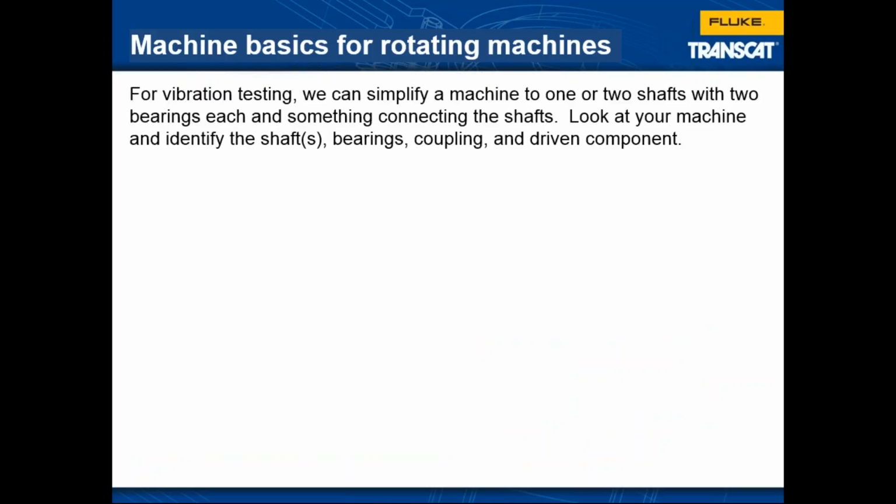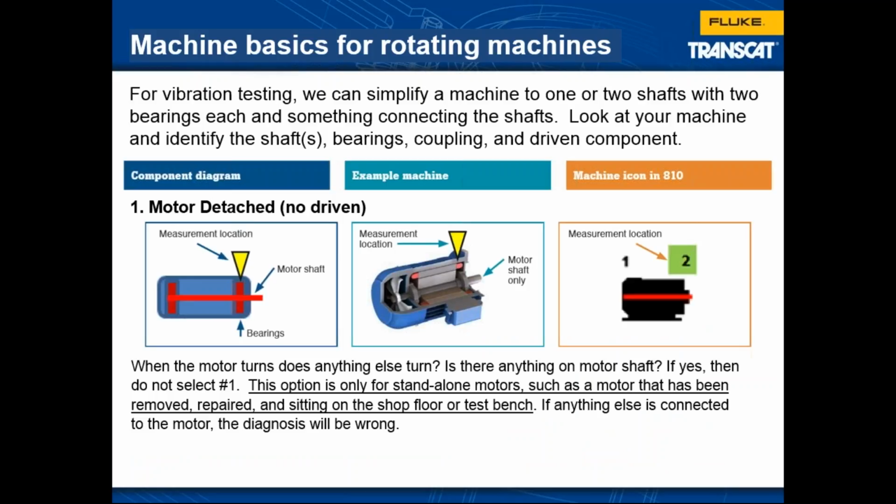Now, we're not going to be able to simplify when we look at machines like turbine generators or gas turbines or paper machines. Those kinds of machines, we're still going to have to use a vibration expert because there's just too much variation. But in simple standard machines, they're pretty basic, and there really isn't that much different from a motor pump and another motor pump.